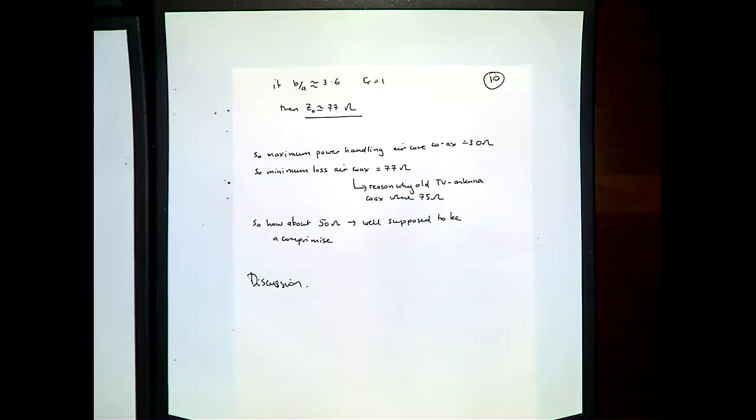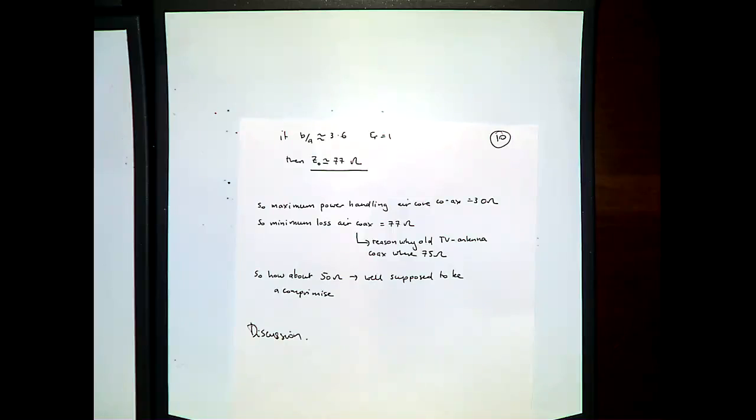I mean, because the test equipment's usually 50 ohms. That's the only reason. I mean, it's bizarre, but it's just what everyone's chosen. People have standardized on it. But the point is, there's nothing magical about it. And for whatever reason, everyone chose it, and every student I know, or even work colleagues, they constantly regurgitate 50 ohms as if it's some God-given fact. And if you don't do 50 ohms, the sky's going to fall in. And the answer is no, it ain't.